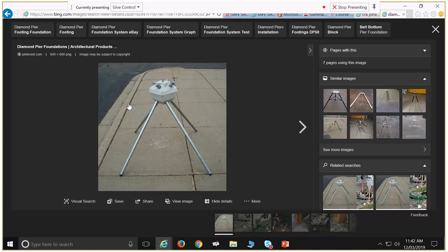So a very small amount of concrete, but of course limitations, or can anybody think of any limitations with that? Space between piers? Yeah, you can rotate them around though. I think that you can plan something like that. They probably don't take up that much room, and you'd have to space out your piers. You do have like 2 metre space between your piers anyhow. If you've got lots of existing pipe work or anything around, there's lots going on under there, you can't see it. Yeah, that could definitely be a limitation, for sure. Labour intensive? Yeah, well, but not really. All your alternatives are quite labour intensive as well.